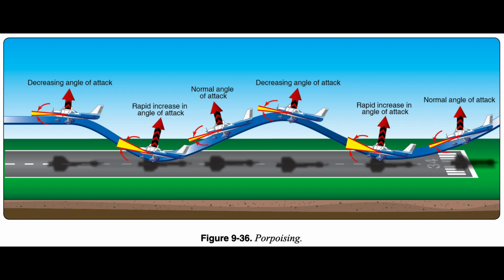Ground effect decreases elevator control effectiveness and increases the effort required to raise the nose. Not enough elevator or stabilator trim can result in a nose-low contact with the runway and a porpoise develops. Porpoising can also be caused by improper airspeed control. Usually, if an approach is too fast, the airplane floats and the pilot tries to force it on the runway when the airplane still wants to fly. A gust of wind, a bump in the runway, or even a slight tug on the control wheel sends the